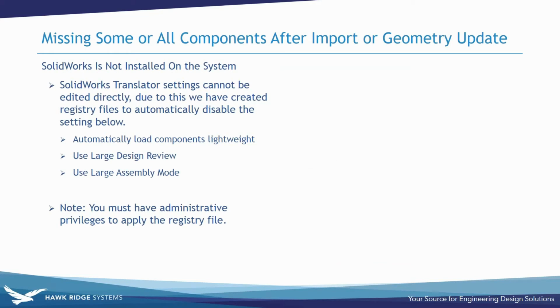As mentioned earlier, not all Composer users will have SOLIDWORKS installed, and instead they will have the SOLIDWORKS Translator installed. The Translator is a background-only process, and we are not able to edit the settings. However, we may encounter the same issue of missing components. To resolve the issue for these users, the registry file for Composer must be edited.